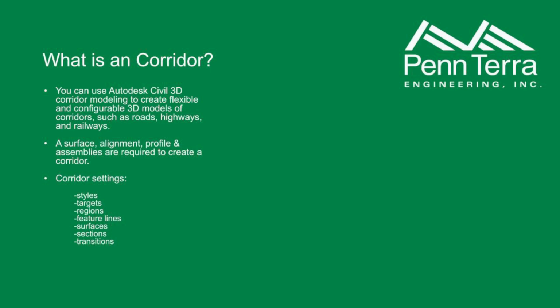It's not always intuitive, but from that standard subassembly added to the corridor, which is made up of the alignment and the proposed profile, you can get a good idea of how your grading will look on your roadway or whatever other linear entity you have, how it looks in the site. You can push, you can pull, you change the profile, it changes the elevation, the corridor reacts, can be rebuilt, and we'll show you the updated surfaces.